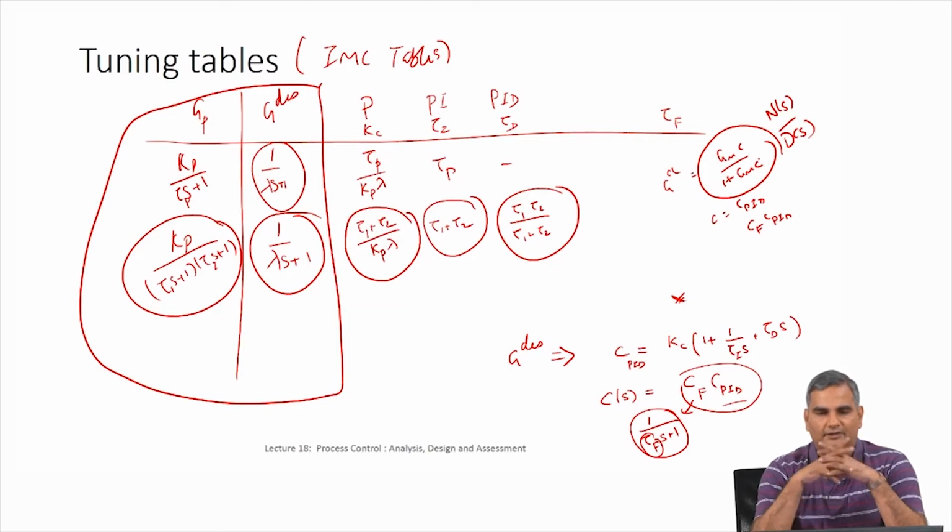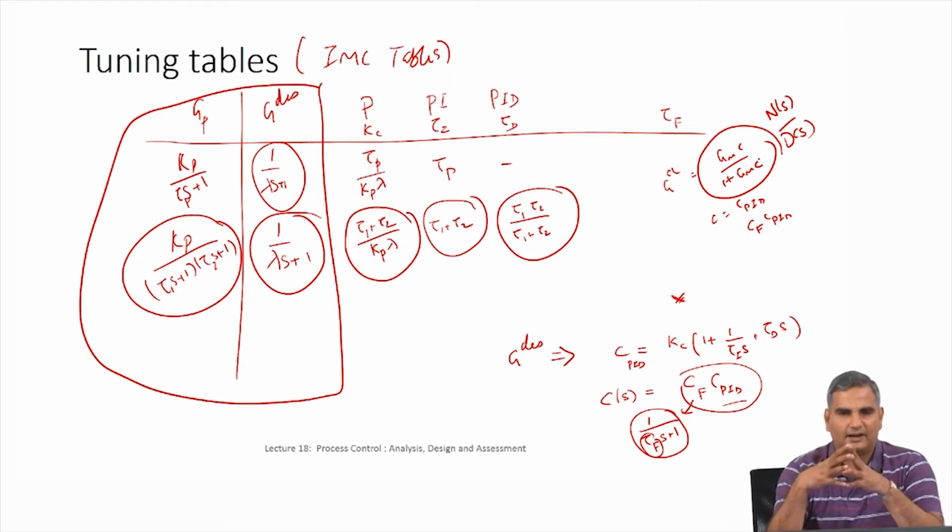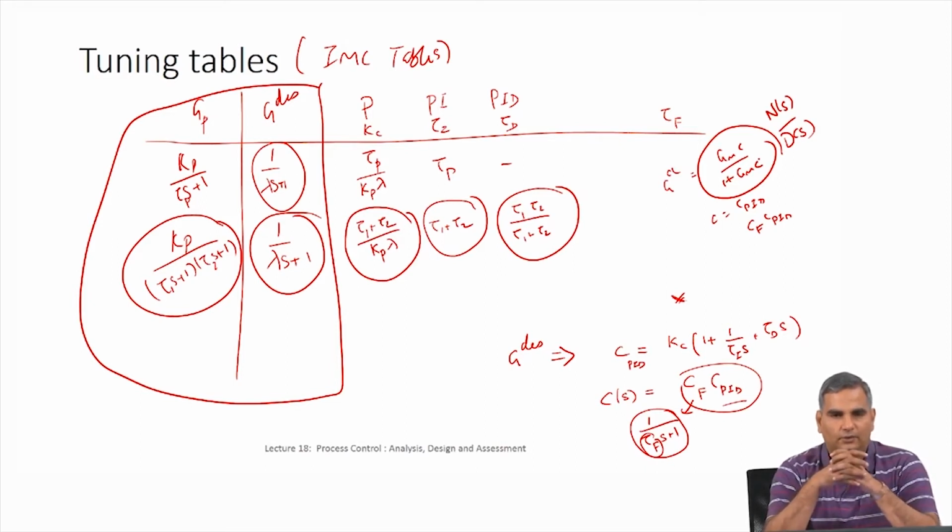Then we said okay, that is the first time where we started by saying a control needs a model. Now the model has been described, the model has been solved, the model has been analyzed. So how do I do control? Closed loop control. So I talked about the notion of feeding back the error and the controller taking in the error as the input and then giving the manipulated variable as the output. That way we were able to close the loop,